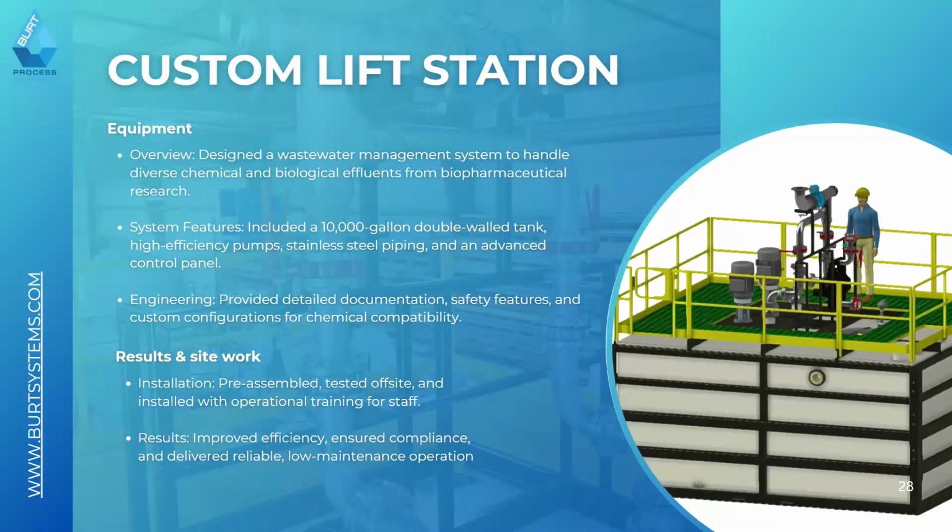And then the next question, Mark, was, is it possible to treat pH within a lift station as a way to save on footprint? Yes and no is the answer. I've done it. You can do it. It really depends on what you're effectively doing at that point. You're oversizing your lift station to give you a residency volume. And rather than pumping it as you would traditionally do based on level, you're always holding back a certain equalization volume in the tank at that point.